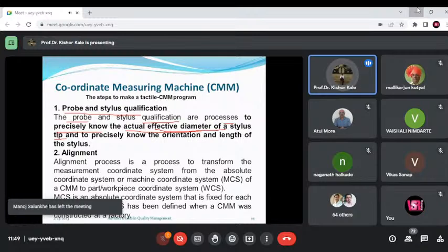Now here in CMM, we have only collected thousands of data points. Here we say lakhs and millions of data points are being acquired by the laser. So data here would be very high. The number of points would be very large in the case of a laser scanner. A good number of points would be there. So the accuracy of this is much more than the CMM. But in some cases, the traceable points are the problem with scanners actually.